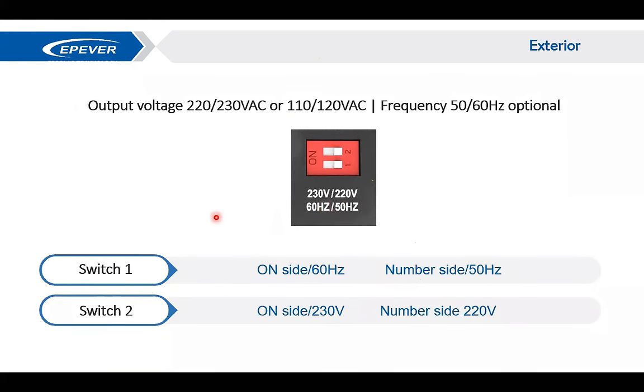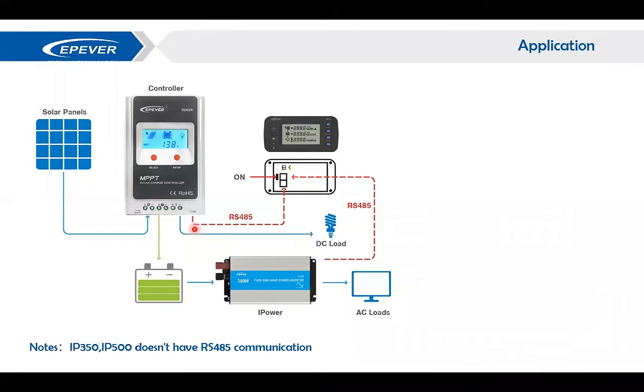Depending on the status of this switch, the output will be different. It is recommended to stop the inverter before making any changes to these switches, otherwise it might get damaged. So always turn the inverter off and then try making changes on the dip switches.